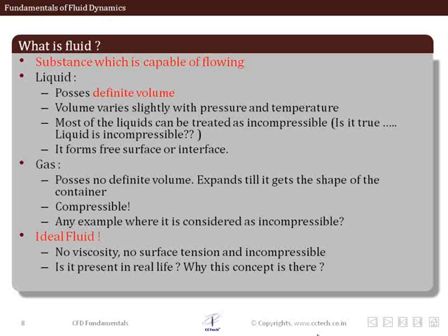Whenever we apply our knowledge of fluid dynamics, we should be careful about understanding when we can consider the flow as an incompressible flow or when we can consider it as a compressible flow. And a liquid forms a free surface under the action of the gravitational force. As far as gas is concerned, it possesses no definite volume and expands till it takes the shape of the container. Most of the time gases are compressible, and in some special cases we can treat gas as incompressible.